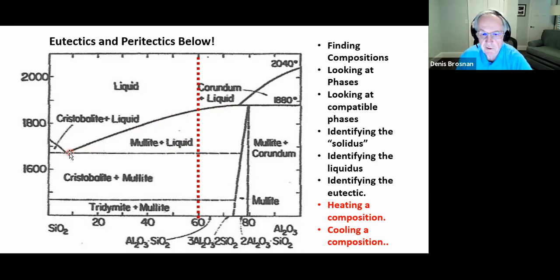Of course, it's solidified at room temperature, but we've got to form liquid and distribute it and use it as a cement, if you will, to bond the particles together in vitrified ceramics. In reaction bonded ceramics, we're going to heat something up and we're going to form a liquid and a mineral. And that mineral becomes important in bonding the ceramic together. And that's true of a lot of refractory products, porcelain products, and things of this particular nature.